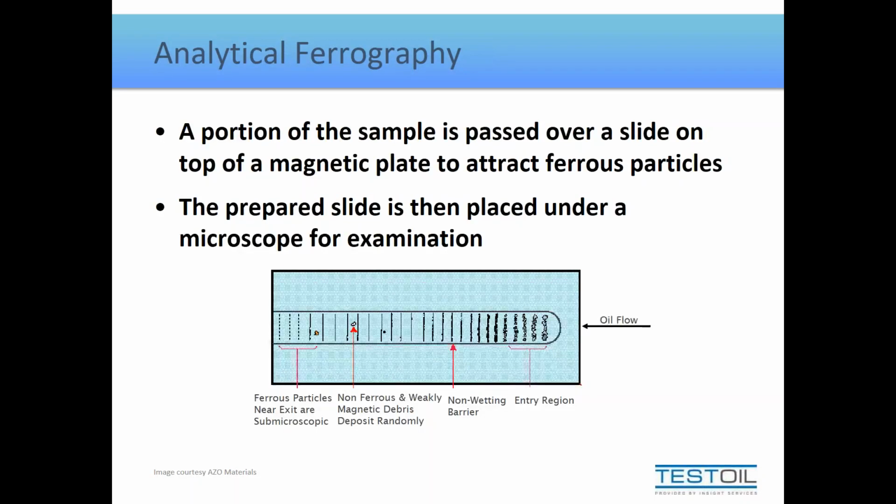So what we typically find is that we get smooth tiger stripes when we see a lot of normal wear particles, a lot of really small wear particles. If we see random spotting, looks more like a cheetah, I always joke that's the wrong kind of cat, and that indicates abnormal wear. So we do expect to see wear particles. We are looking to see what kind of wear particles we have. So this slide is analyzed under the microscope at the room temperature which it was created at.